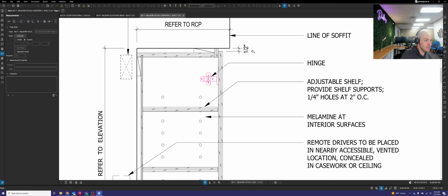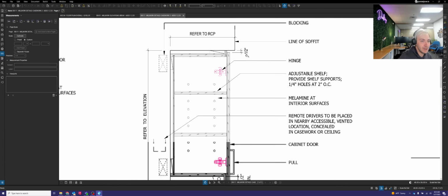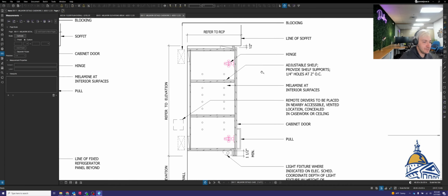However, we know here at Onsite that our upper cabinets need at least 3/4 of an inch to be lifted up and put in place when they go to install it. So even though the architect shows this at 1/2 an inch, we do have to modify this to a 3/4 inch gap because we can't lift that up and drop it onto the cleats back here with a 1/2 inch gap. It just won't work. So we have to change that, and that's just what it is.